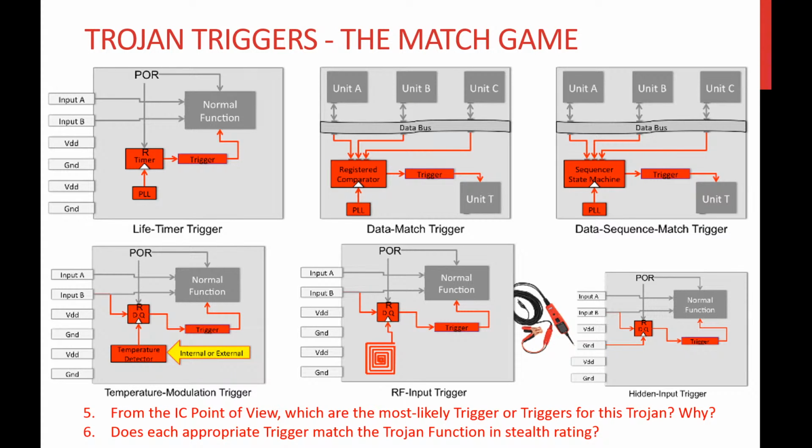The setting up of the action or Trojan payload to be accomplished can be done either by establishing the settings and compare data values through the I2C port, or if the Black Hat designer put an effort into thinking through the usage scenario, by special command packets through the normal data path.